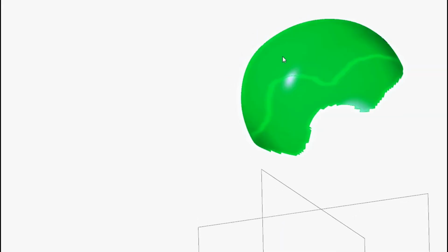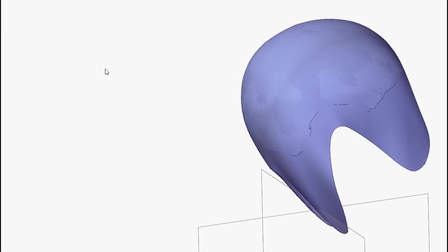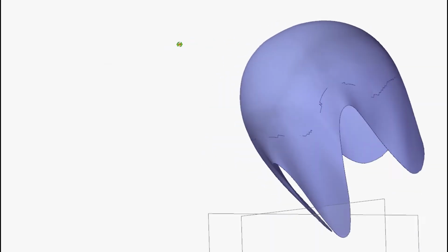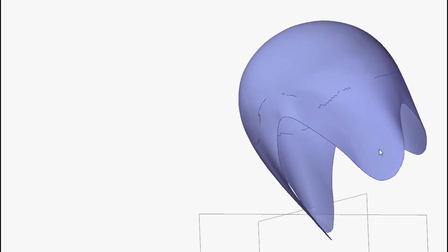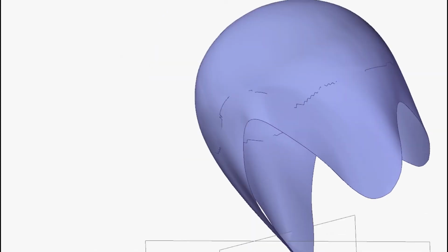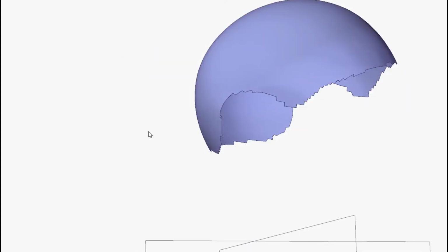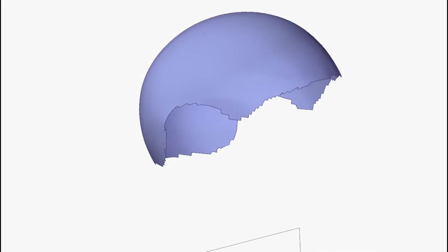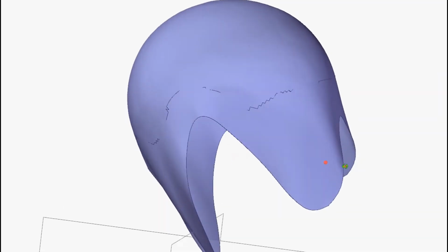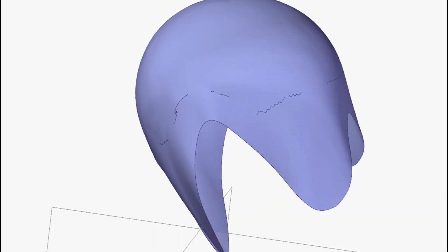Now the reason you need to do this as opposed to just using the mesh to then create a solid model is that it won't provide good results and surface finish. The mesh is just graphic data, so you may run into numerous issues when trying to modify this once you've made a solid body out of it. The B-spline surface will have proper data, so we can have good surface finish once we turn it into a solid body, and we'll also easily be able to modify and make changes to it without errors.